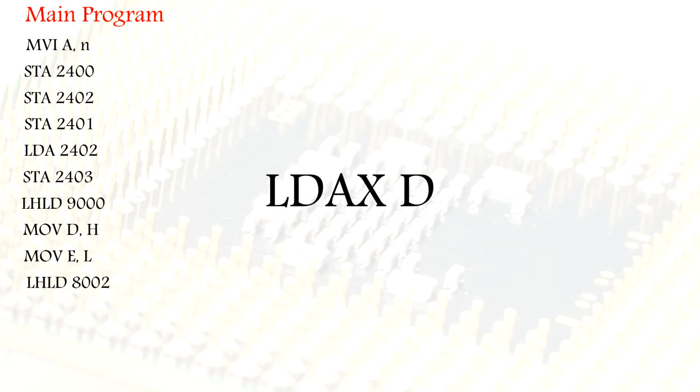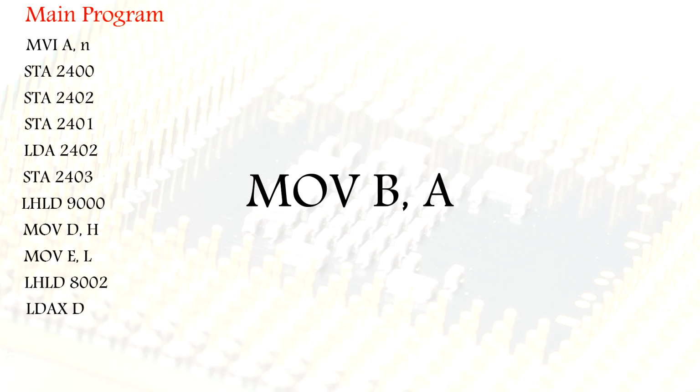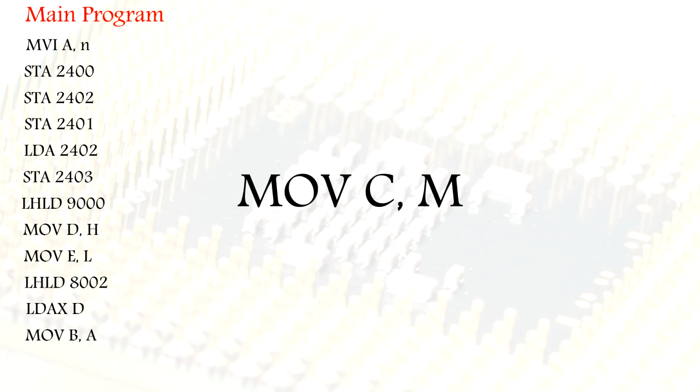Now using this command LDAX D, whatever was in the DE register pair is carrying the memory location, and the contents of that memory location, 4501, will be loaded into the accumulator. So the contents of 4501 are loaded into the accumulator using the LDAX instruction, and that content of the accumulator is now transferred to the B register.